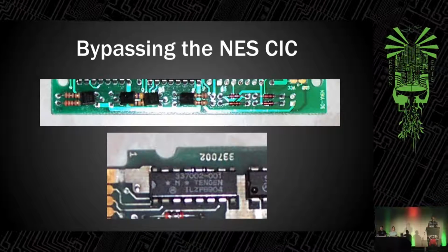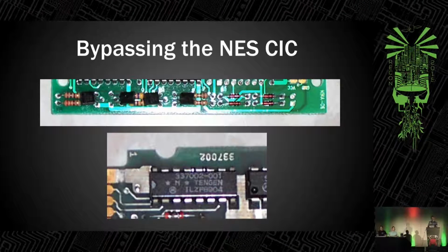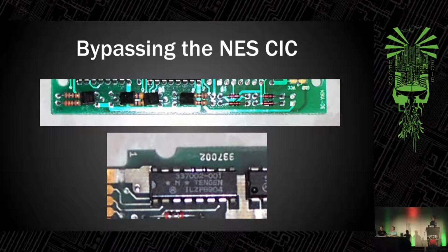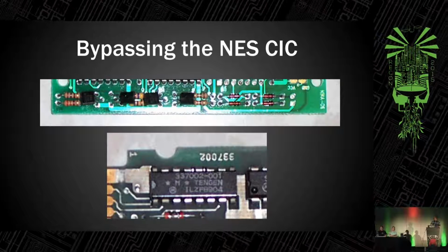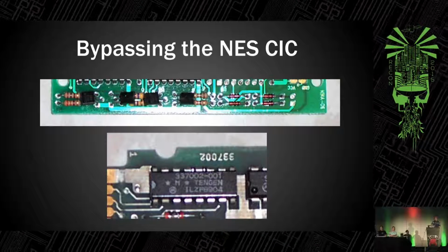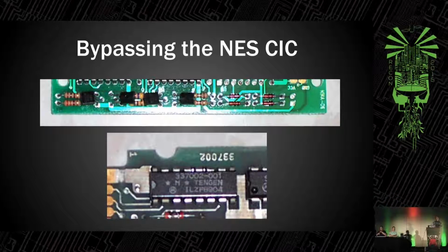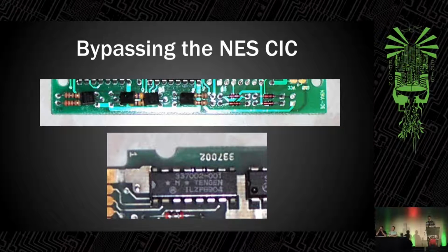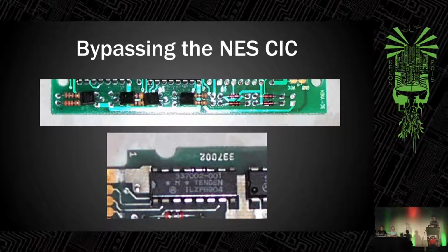Now, there were pirate games for the NES, and there's a couple ways that they did this. It was pretty interesting, I think. The picture on the top there is part of the game circuit board, and there is no lockout chip. Instead, there is a boost regulator, which is just a circuit that generates a very large negative spiked voltage, and instead of talking to the chip, it just punches it in the mouth and then shuts it up. Wow. So it's definitely not kosher. It did work, some of the times. Sometimes it just kills your console.